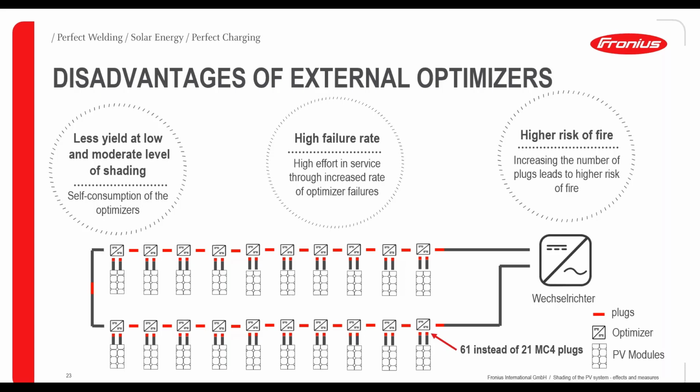So it's 3 times more, 61 instead of 21 MC4 plugs. And that's actually also a higher risk of fire in that case. So please also make sure to consider that when you plan the system.